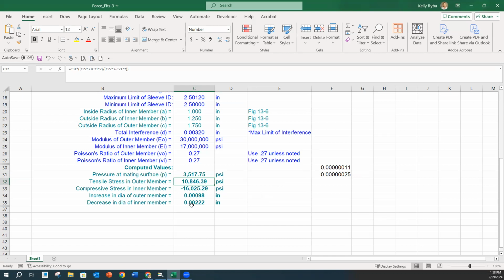But what it's telling us is that we're going to maintain pressure. We're not beyond the yield point of the material. So we haven't exceeded it, the grain structure is still intact in order to keep these together. That's where we're at when we compare to that yield strength. Haven't gone past the yield point. Got it. Okay, that makes sense. So if you took them apart, theoretically, they should spring back to the original size. Correct. Yep.